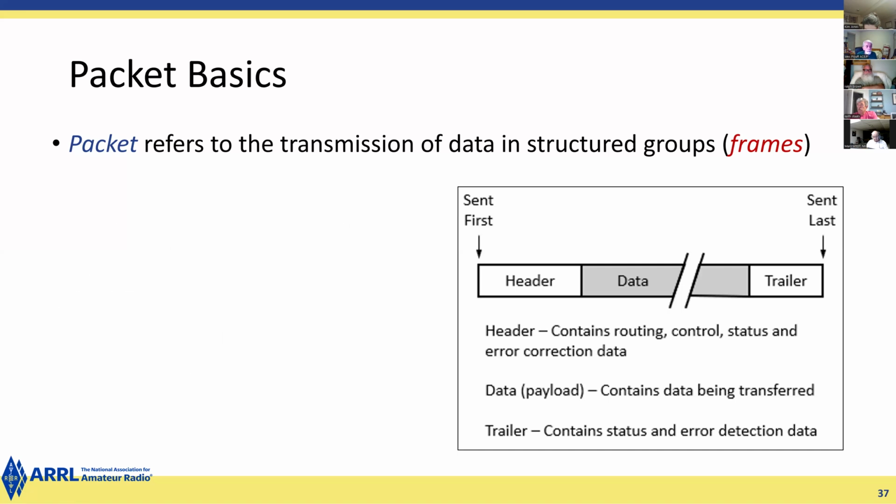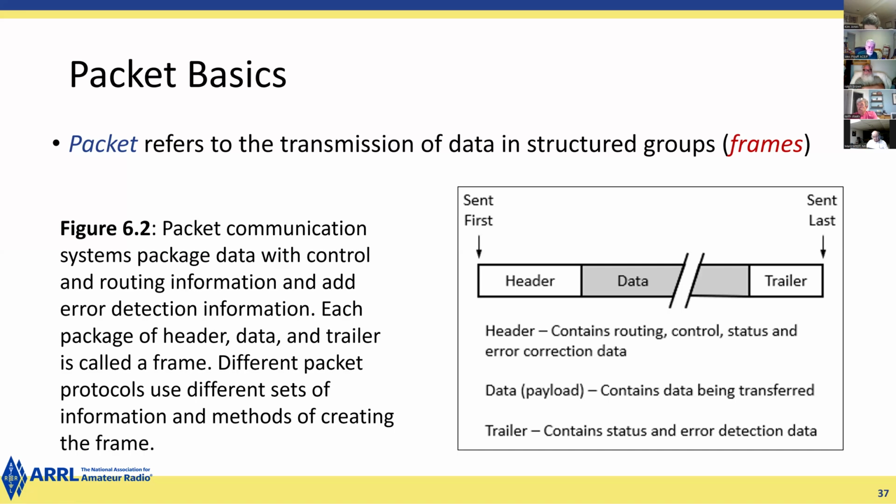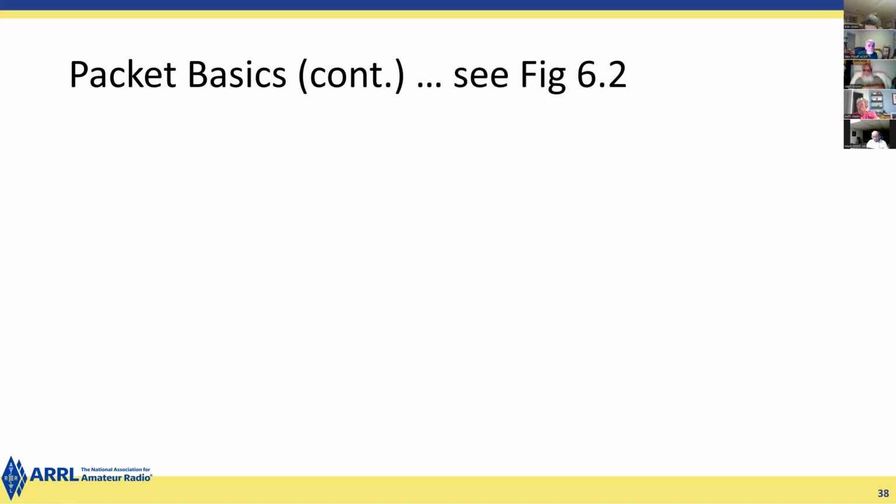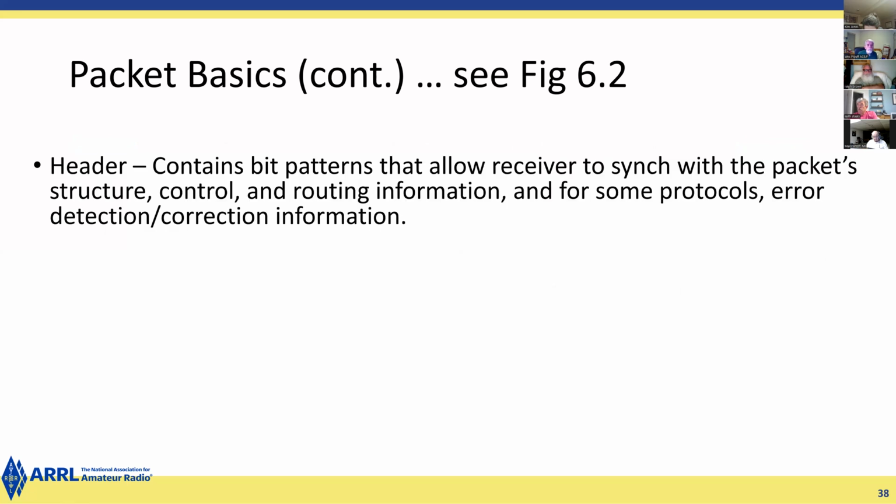So first thing that you have to do is when a packet transmission starts, the receiver has to synchronize with the transmitter. So there are usually fixed bit patterns within the header that serve to synchronize the receiver to the timing and bit pattern of the transmitter.